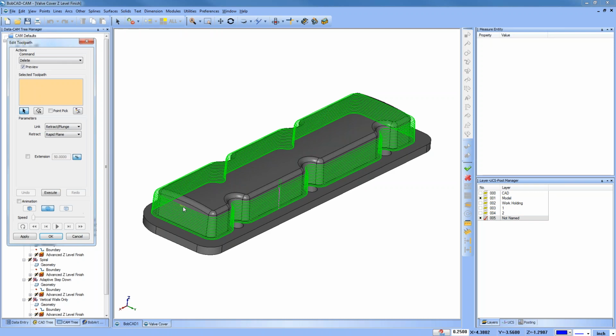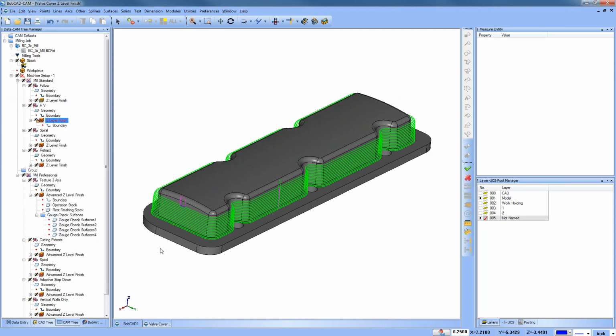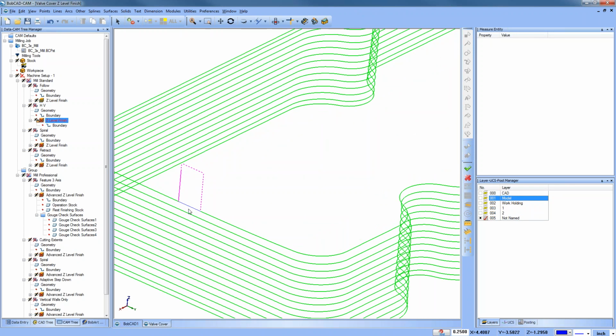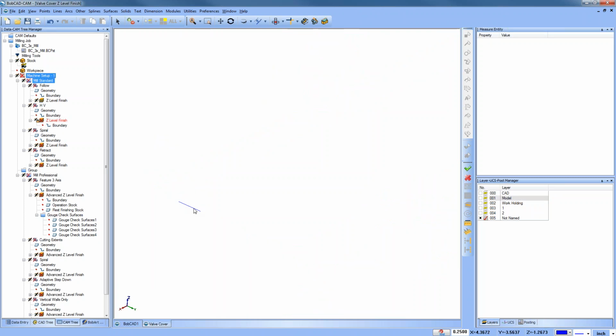Here you could select a section of that toolpath, and then you can use this button right here, Convert Selected Toolpath to CAD. It's going to say that it did it. We can say OK, and then what you will see is that this line right here is now geometry. So if I go away from my toolpath, you can see that's now geometry. And that is a trick that you can use with the new Toolpath Editor.